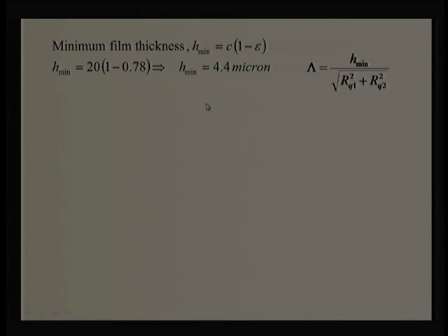So, that way feed pressure is going to increase film thickness, is going to bring us from the mixed lubrication domain to the hydrodynamic domain. So, we can do calculation, and when we do calculation we find out whether everything is fine or not. If it is not, then we should use some sort of feed pressure to supply liquid to cool the liquid lubricant or reduce the temperature, make the effective viscosity more than what has been estimated, and get the results.